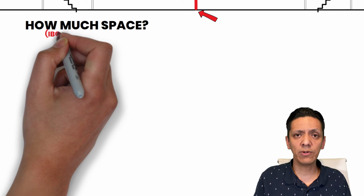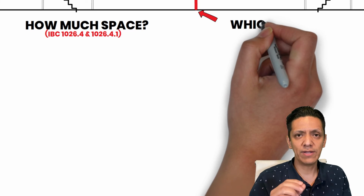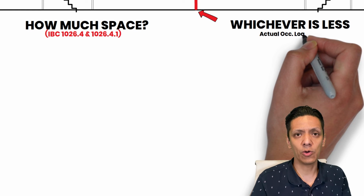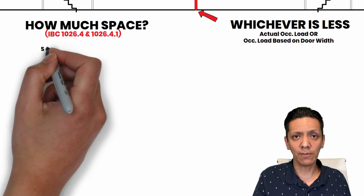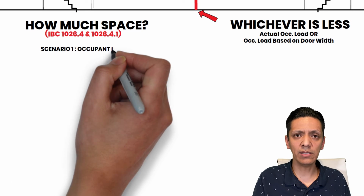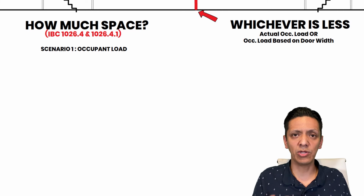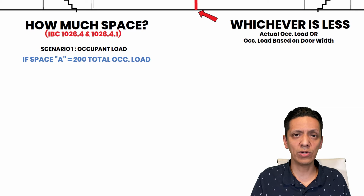And to answer this question, we actually have to have a look at two options. And from those options, we have to select whichever gives you less occupants, either the actual occupant load or the occupant load based on the door width. The first option or scenario is when you take a look at the actual occupant load of the space. For example, again, we're talking about space A exiting into space B, but you have to do this vice versa, right? But if space A has 200 occupants, then that's your occupant load.